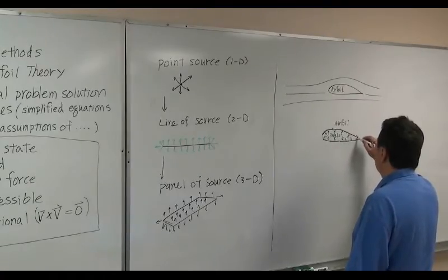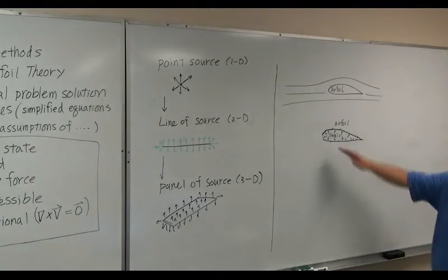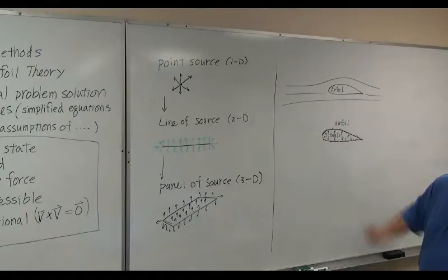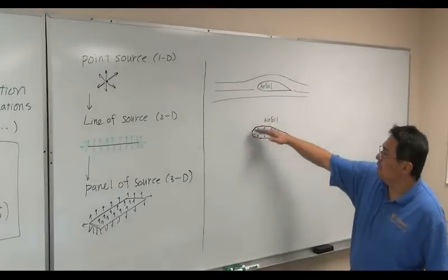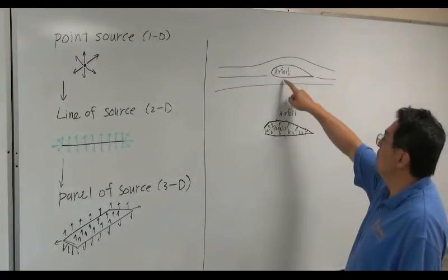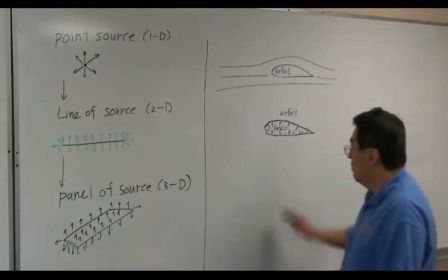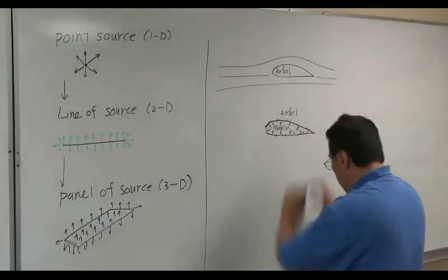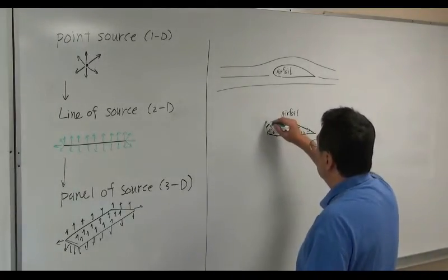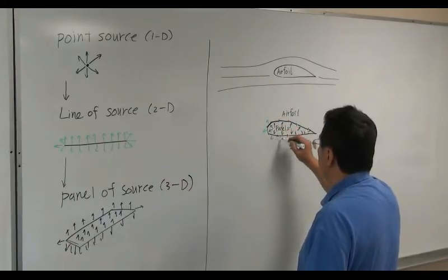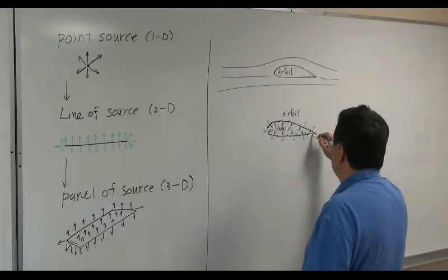Okay. So in my particular case, I'm using only 13, but suppose you use 100 panels of small tiny segments, each segment is straight. If you use 100 panels, it's going to be a fairly smooth surface that fairly closely represents the airfoil shape like this. So this is the body created by source panels, and each one of those panels creates a velocity like this.